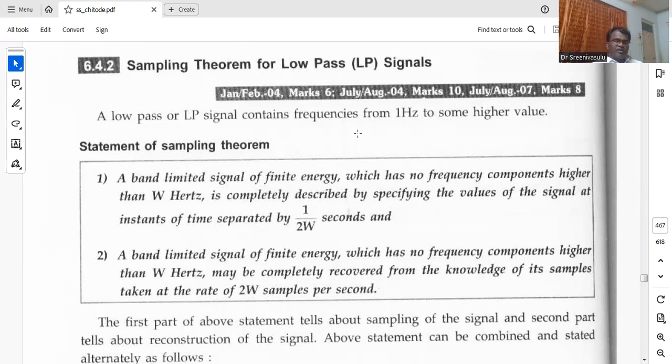Then finally, at the receiving end, it is not going to reconstruct our original signal. To avoid all these problems, for the maximum frequency present in the signal, we select the cutoff frequency of a low pass filter.